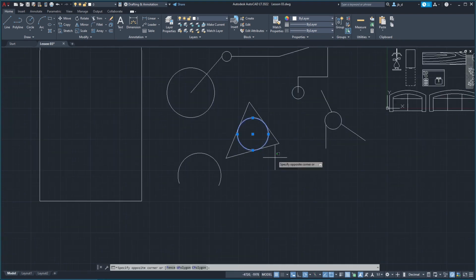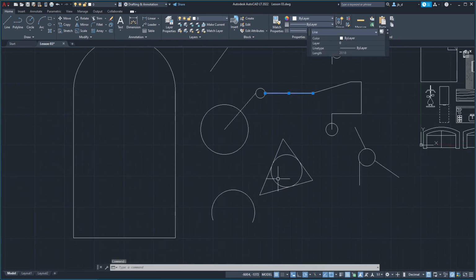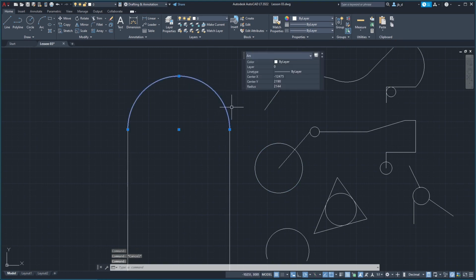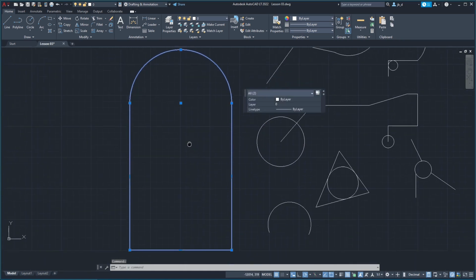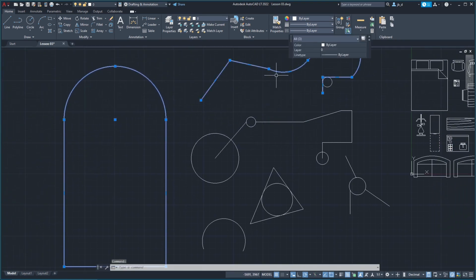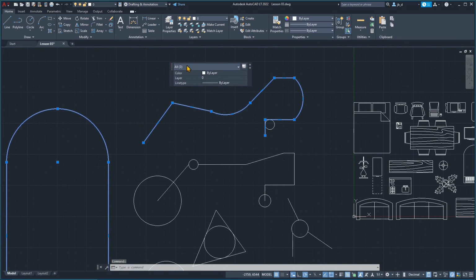So what if I want that to be always appearing? If you click there, you can turn this switch on. By default, I think this is off. Now that it's on, every time I click on something, quick properties is going to appear. But be careful, because it appears about the object that you are selecting. If you select more objects, only the common parameters are going to be displayed, and then you have this drop-down menu where you can select the arc or the polylines and so on.